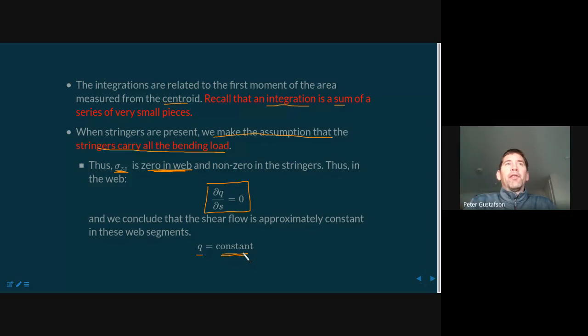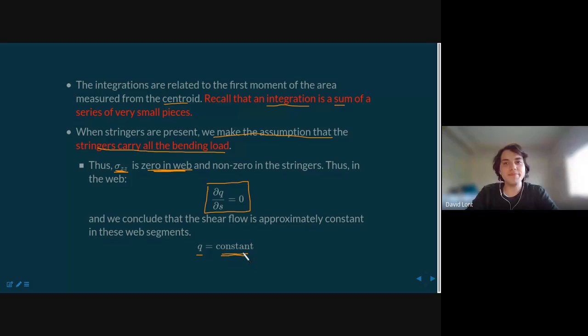And so what does that mean? That means that the principal torsion carrying members, the shear webs and the closed cells, actually carry less torque than what our theories would assume. So in both of these cases, we end up with a conservative assumption on the amount of stress that's calculated given the loads that are present. That's not quite as clear a rule of thumb as I gave you with the length to width ratio and some of the other ratios we've used along the way, but I think it's quite a pragmatic way of thinking about it. Does that answer the question, David? Yeah, thank you. You're welcome.